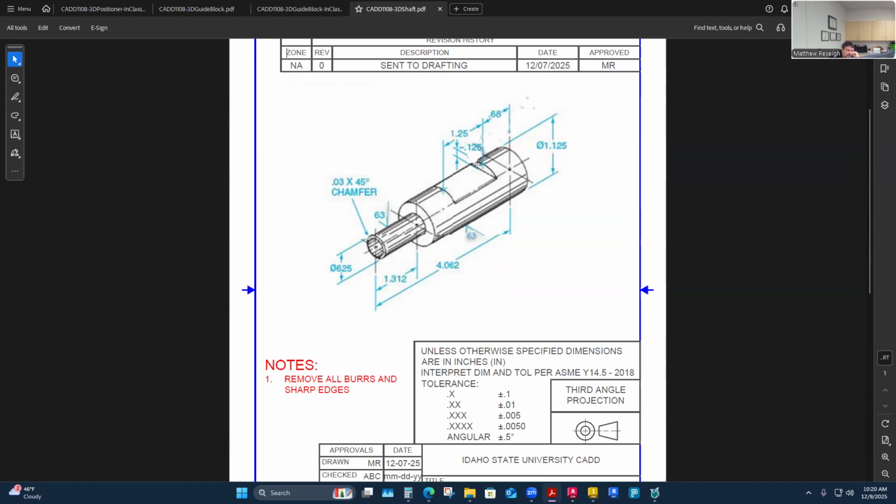And then I'm going to go over, and I'm not going to put in all these details, but I want to go over however long this is before it goes down. I don't think it's explicitly given on this drawing. It's not giving me that length, but I am giving it here. So I might come back to this end from this center axis and draw up a radius. Half of 625, that's 5/8. Half of 5/8 is 5/16. So that's going to be 5/16 radius up, and then it's going to come back 1.312, and then it comes up and then back to that point there. So I'm going to draw that in as just half of it, essentially.